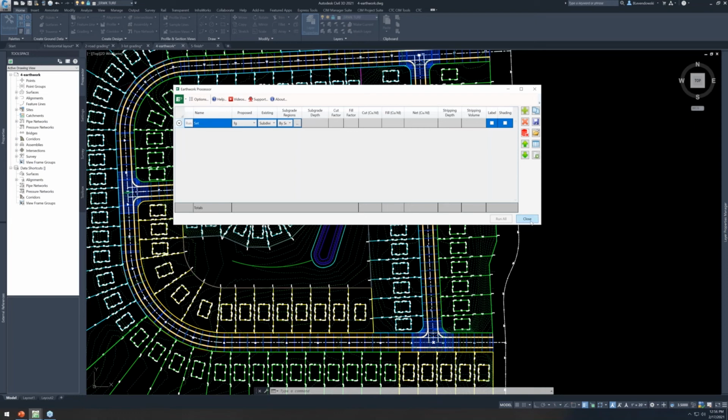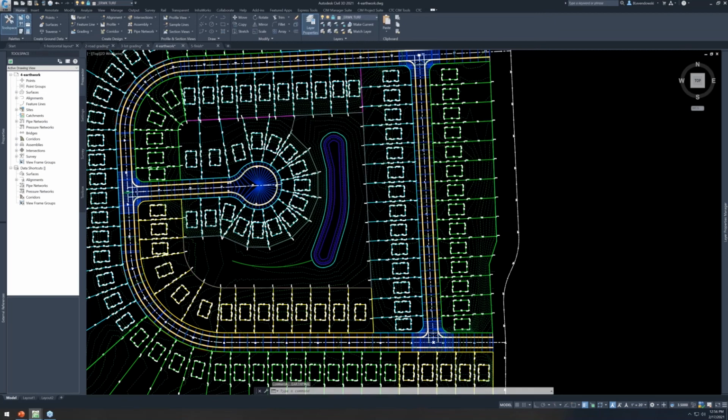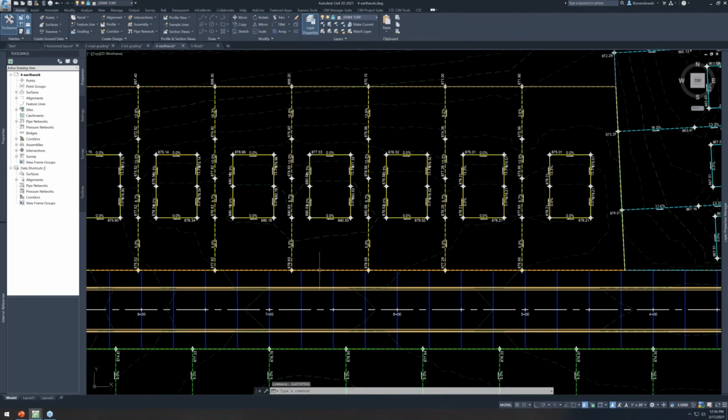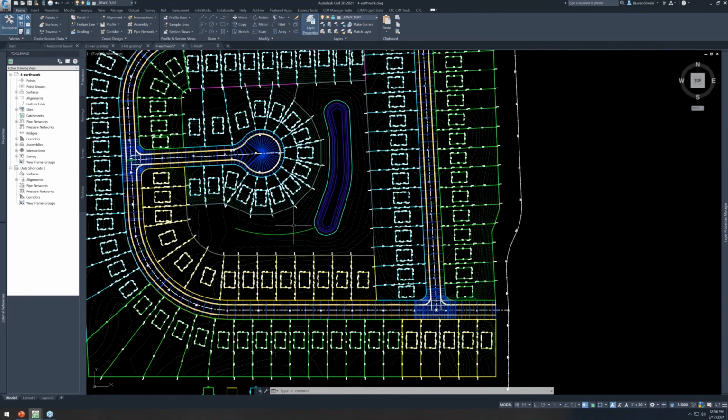Because certainly the triangulation in that lot surface would have triangulated across the road, but it would have just gone flat from right-of-way to right-of-way. Okay, if you paste your road surface second, that will trump, and the road triangulation will control in that area.